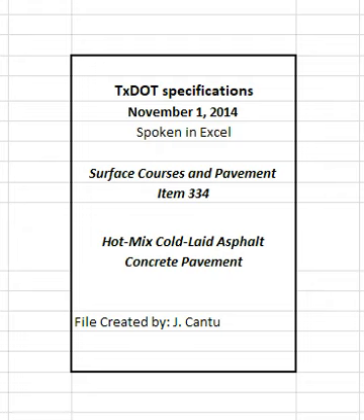For sources not listed on the department's BRSQC, build an individual stockpile for each material. Request the department test the stockpile for specification compliance, and, once approved, do not add material to the stockpile unless otherwise approved. Provide aggregate from non-listed sources only when tested by the engineer and approved before use. Allow 30 calendar days for the engineer to sample, test, and report results for non-listed sources.